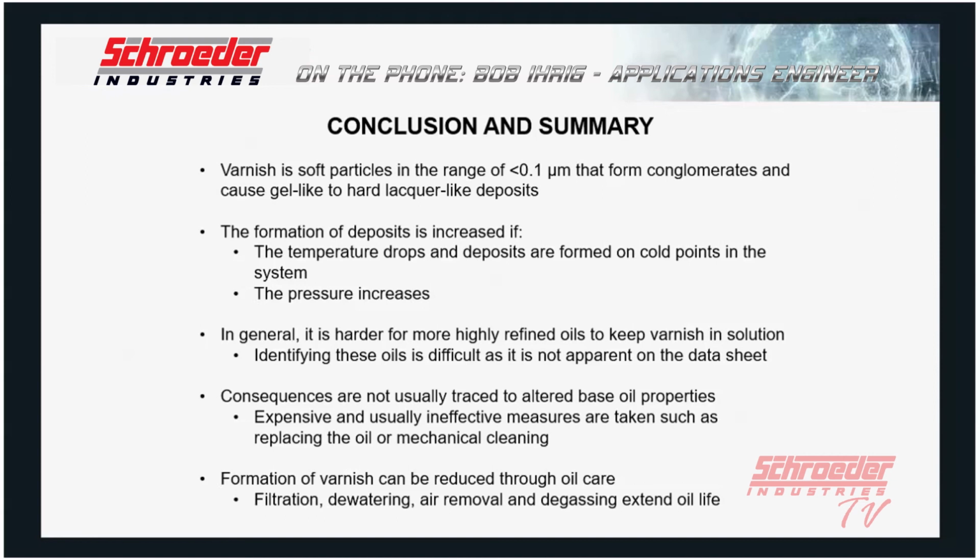And finally, and this actually was something we talked about more towards the middle of the presentation, before varnish exists, some of the steps that can be taken is fluid conditioning in itself, and that's particulate filtration, dewatering, and degassing. For obvious reasons, it's really kind of a domino effect as far as premature oil degradation.